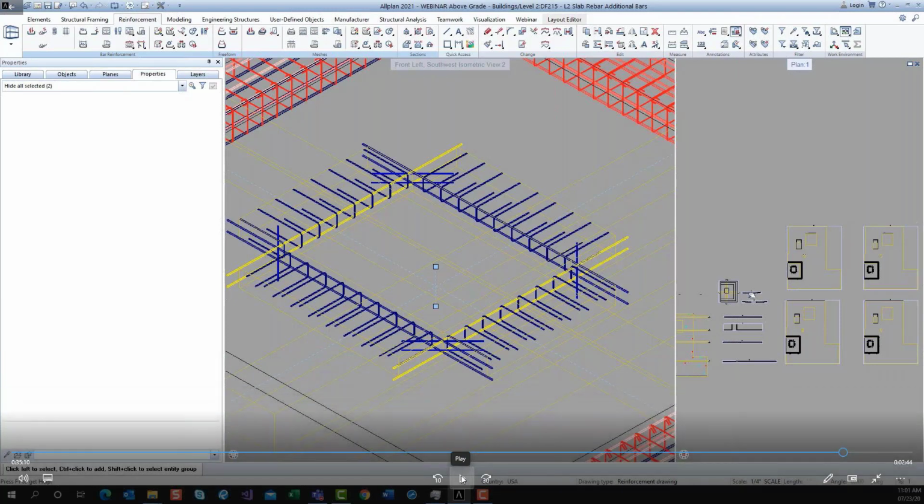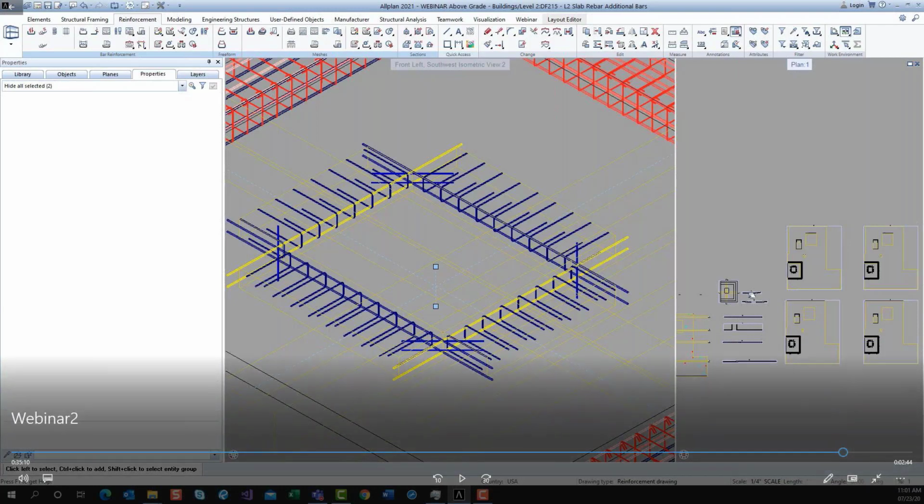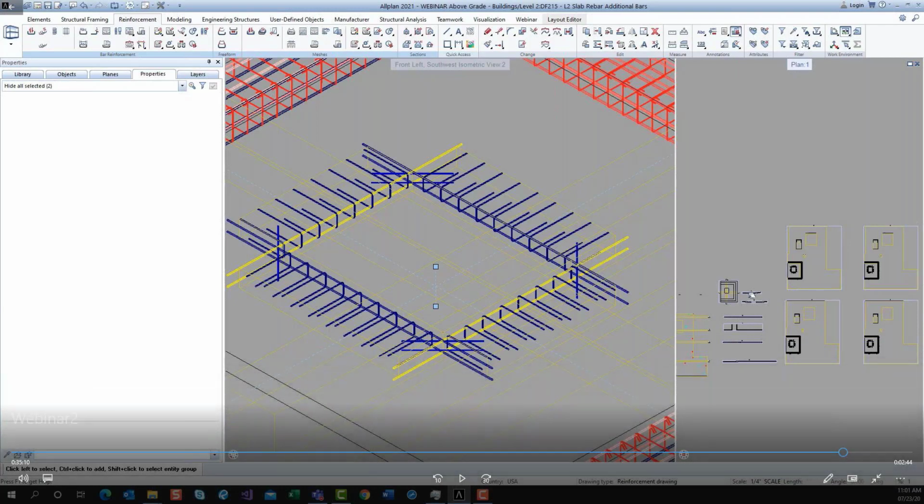So the last thing we're going to wrap up here with is we have this information. We have this now, typical slabs. This happens to be level 2. The next thing I'm going to show you is I have this exact same slab for level 3, okay? But I need the same drawing files, I need the same information. Sometimes on the layouts, you would just say level 2 and level 3 typical, et cetera. But from a standpoint of being a project-driven software, you want to have individual bars. You don't want to do a 2 times on a layout. You physically need to create those bars again, okay? And maybe you want to do the drawings. Maybe you need to tweak a little bit on the 3rd floor.